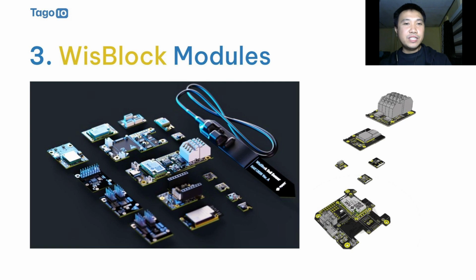On the left side, you will see different modules that we offer. These cover different types of sensors, like environment sensors or non-contact proximity sensors. We also have interfaces, as I said, like RS485, 4-20 milliampere protocol, CAN bus, SDI12. These interface boards allow us to integrate third-party sensors and probes to the WisBlock. Let's say you have a soil moisture sensor from a third-party vendor that we do not provide, you can still use WisBlock for that. We also have some standard I/O interfaces like an I/O expander if you need more I/O pins. We have PWMs if you need to control motors or LEDs.